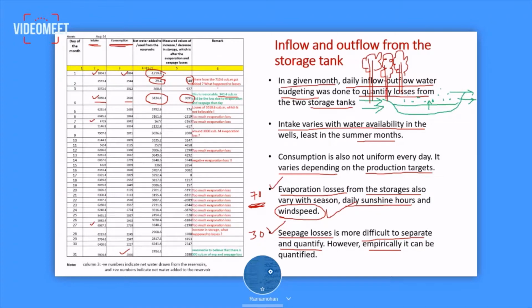So in fact apart from the windbreaker suggestion, we also suggested this, because Tadipatri town is very close by and a lot of sewage is generated, and all that sewage goes into a treatment plant. Currently only primary treatment is done, and then partly treated water is coming out and being disposed. So why not the Arja steel plant install further treatment facilities there in the same premises, make it tertiary treatment, make the water quality suitable for their use, and bring that water and use it for various purposes, so that their dependence on the groundwater will come down for a period of time. So that is how the water audit was conducted in this industrial scenario.